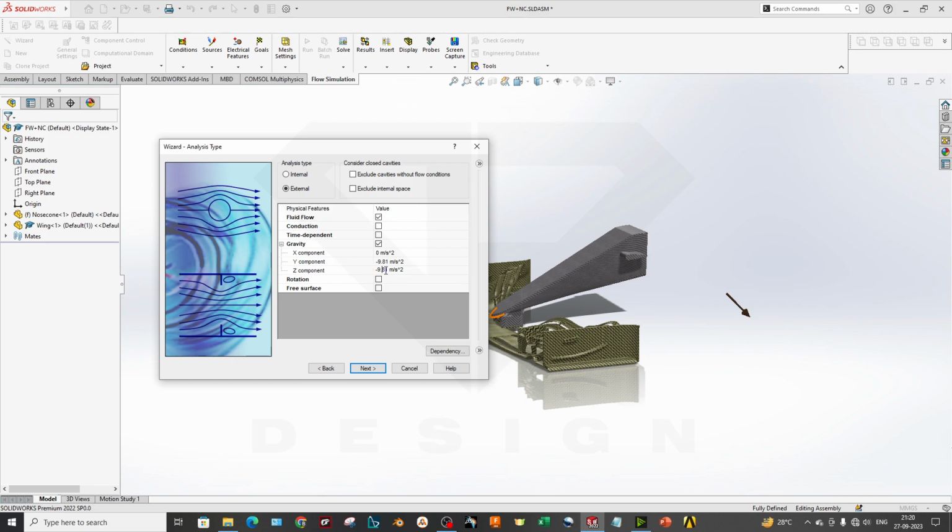What it tells, I will click it to 0. Okay, fine. So this is my Y direction right now. Rotation, I don't have any rotation region in this simulation. Rotation region will help you to perform a turbo machinery simulation, just like a turbocharger, supercharger, any type of blower, or wind in a wind tunnel. So that kind of rotary objects you can add in the rotation.